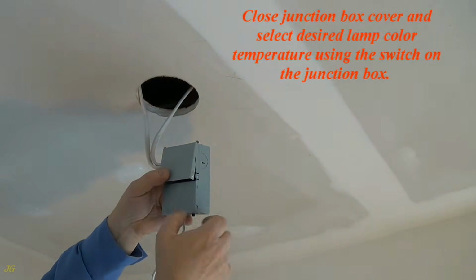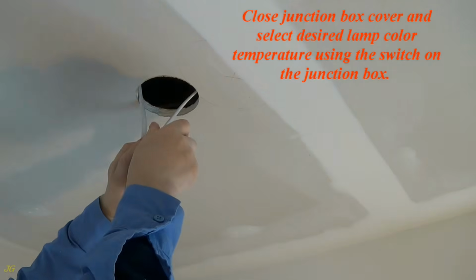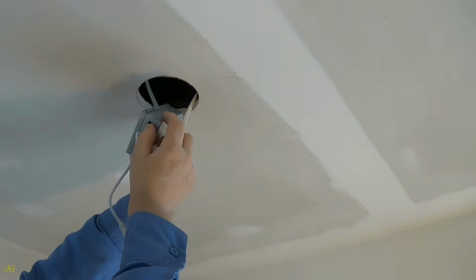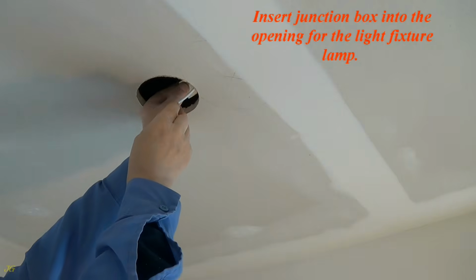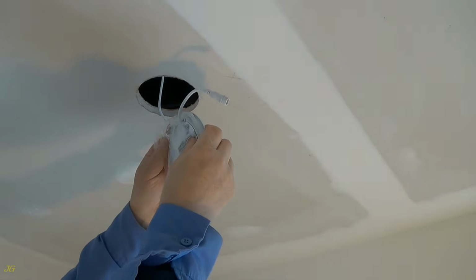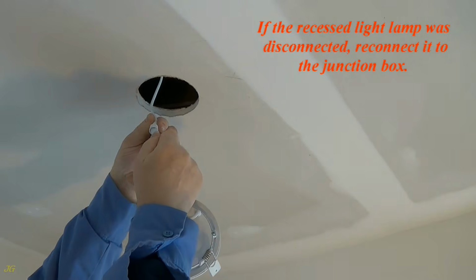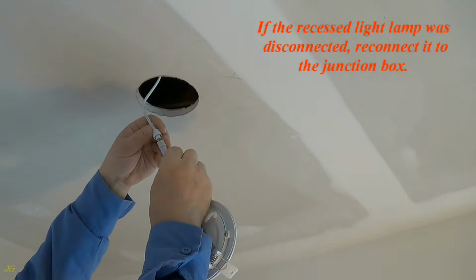Close the junction box cover and select the desired lamp color temperature using the switch on the junction box. Insert the junction box into the opening for the light fixture lamp. If the recessed light lamp was disconnected, reconnect it to the junction box.